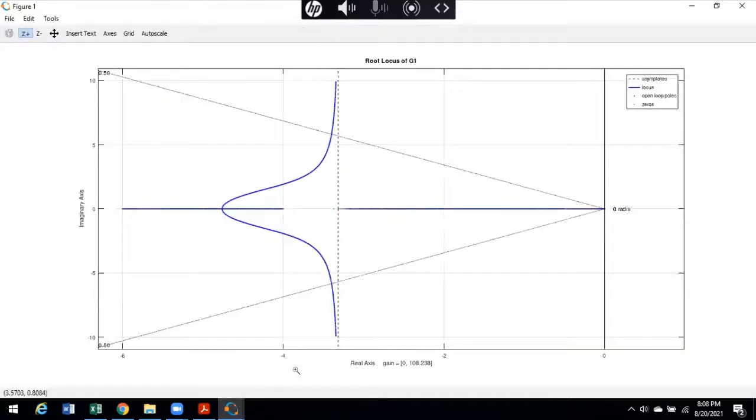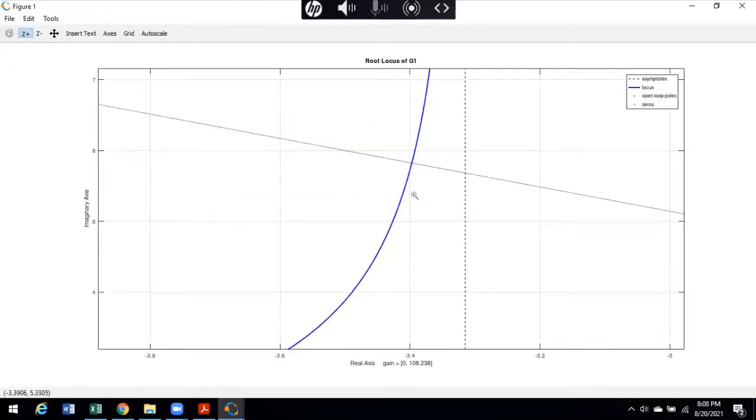So let's find this point there. What is intersecting your damping ratio line and your locus? You find that this point is, if you look down there, at minus 3.395 and 5.817. So it's very close to what you have worked with. It seems to be okay.